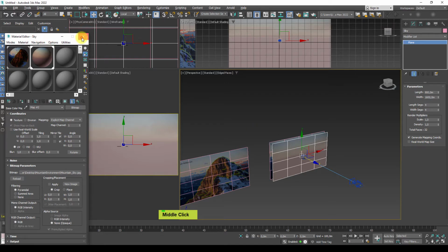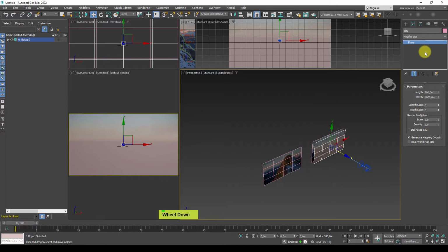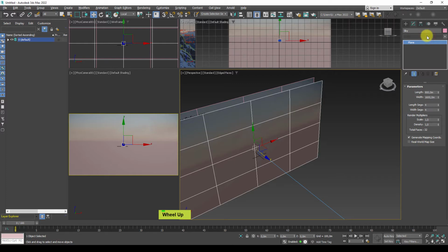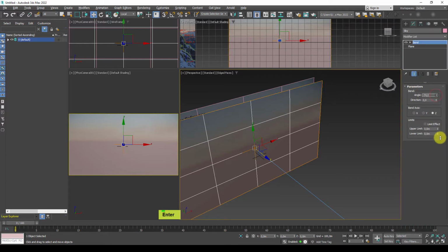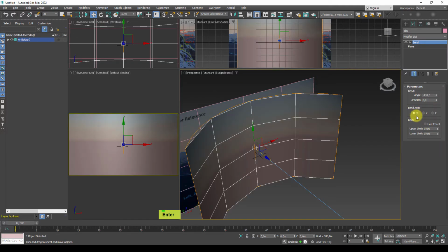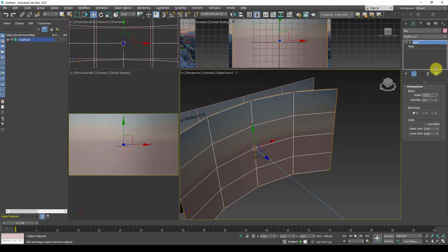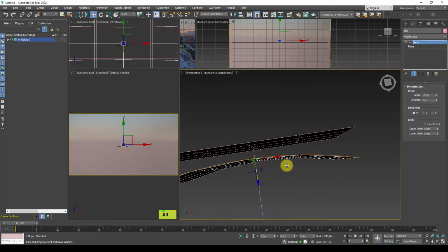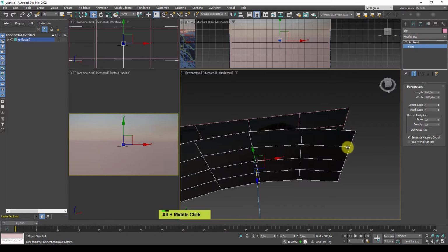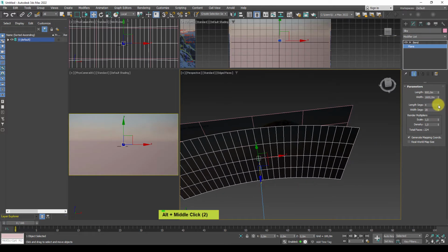Okay, to add some 3D effect, we can actually bend this a little bit with a bend modifier. Hit enter, start bending along which one? Yeah, x-axis, but it's negative. Okay, we don't need that much, just a slight bend. And to make it a little bit smoother, these segments are fairly low, so let me switch to plane mode and increase the segments in this direction.